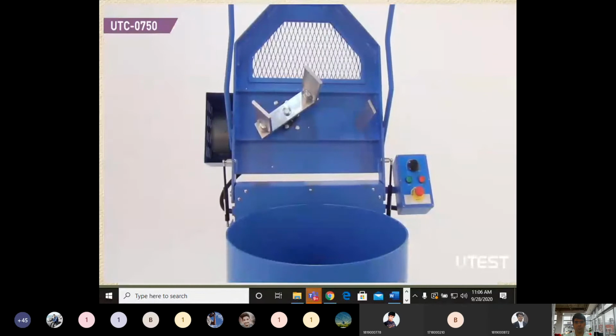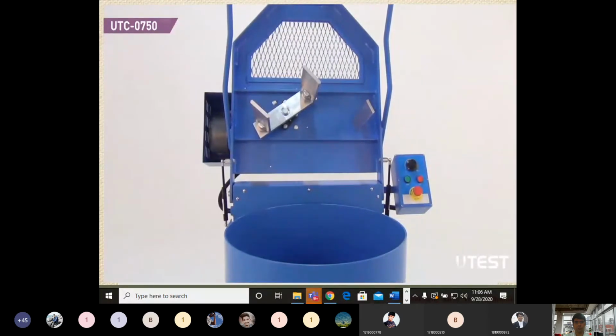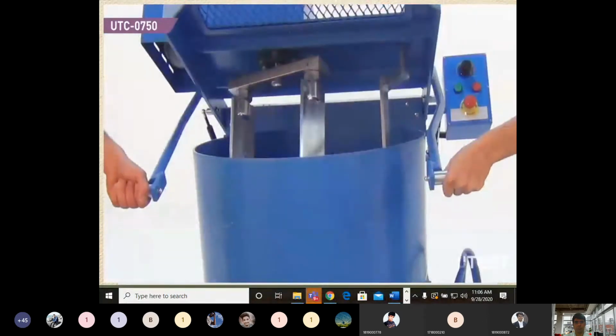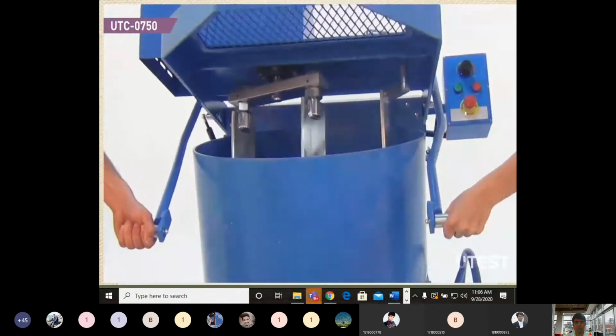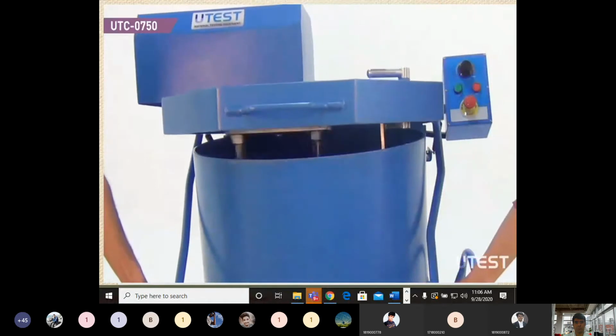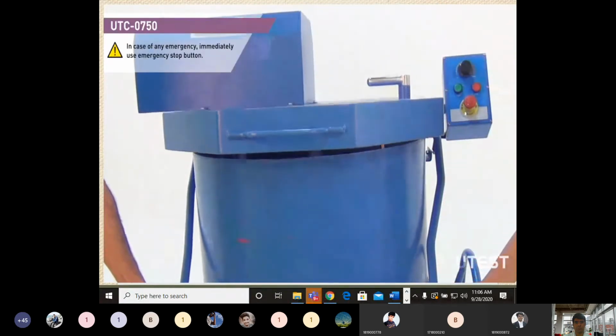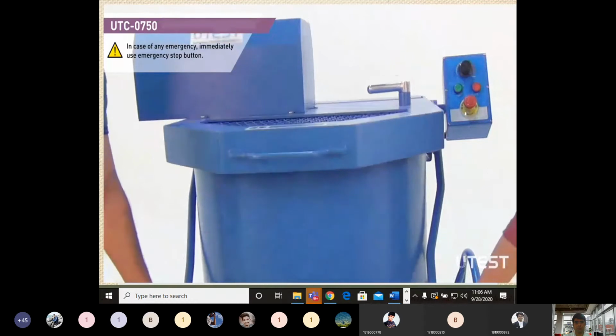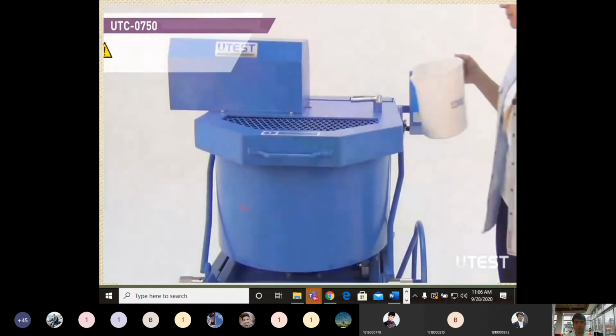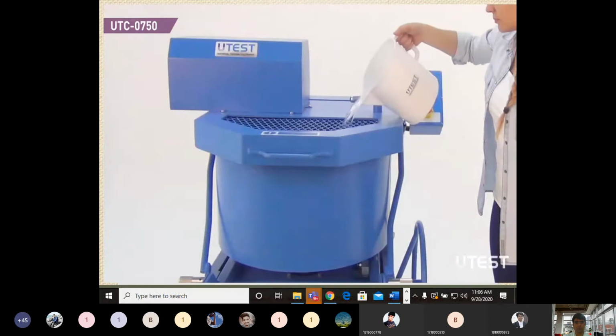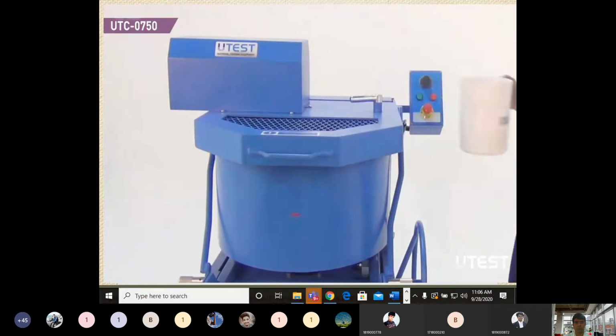If the cover is open, the pan and the blades will not operate as a safety feature. The position of the cover is detected by a safety switch. While closing the cover, push the start button and arrange the pan speed by using the knob. This is important to ensure smooth start-stop of the mixing operation. Lock the cover after it is completely lowered. Material addition is possible from the grid window without stopping the mixing operation.